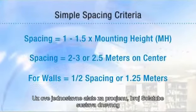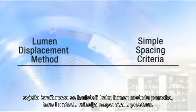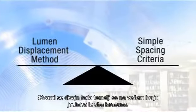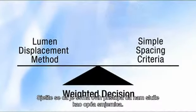With these easy estimating tools, the number of Solatube daylighting systems are calculated using both the lumen displacement method and the spacing criteria methods. The actual design is then based upon the higher number of units from both calculations. Remember, this approach is intended to serve as a general guideline.